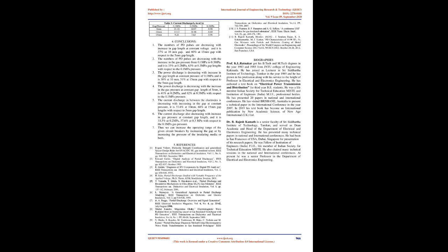to 16.18 W. The 2D graphs of PD indicate the discharge current, discharge power, and number of PD events per second against the phase angle of the voltage waveform. The data has been recorded in tables 1 to 3 for different gap lengths and different gas pressures. The color variation in the PD graph indicates the variation in the PD activity over the phase angle variation of the applied voltage.